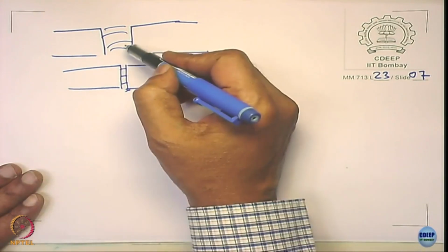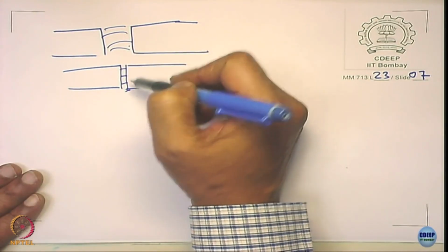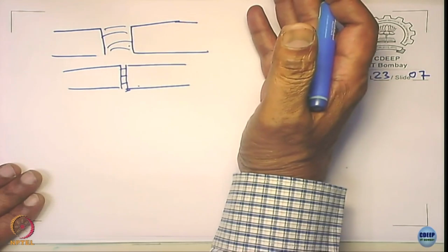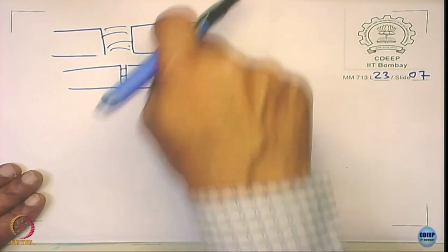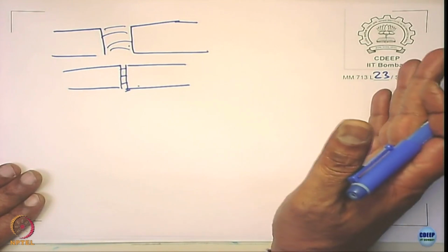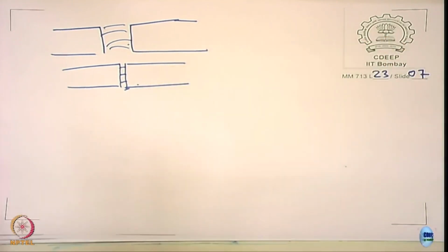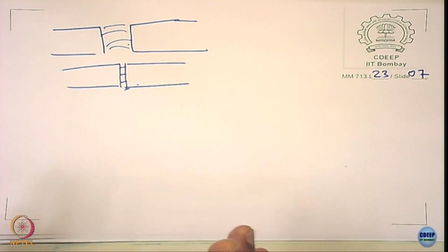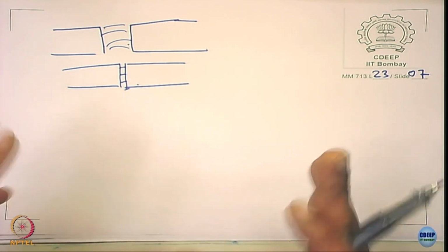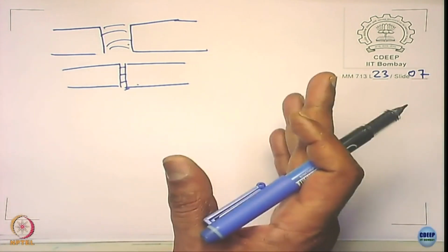The cooling cycle here and here are different, so the way they sensitize is going to be different. Am I right? Similarly, the conductivity of this metal and this is different, so things will be different. So we need to superimpose the sensitization kinetics with respect to the science of the welding process. Then only can you understand how weld decay occurs, right.